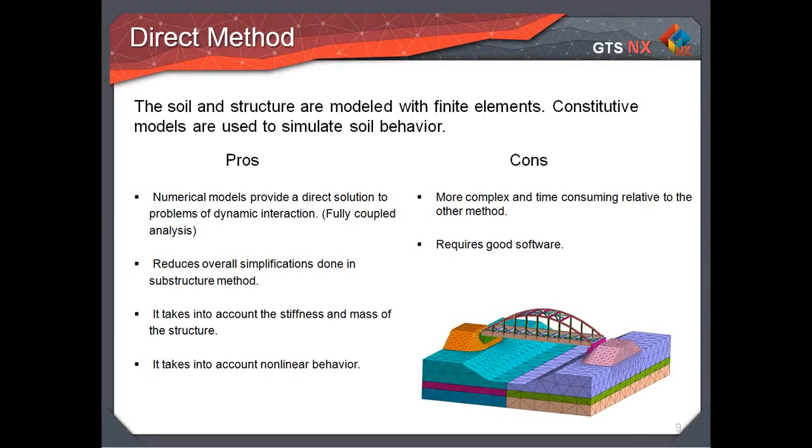There are some for rocks, like the generalized Hoek-Brown, but then there are some for clay, like the soft soil creep or Cam-Clay constitutive models. So there's a whole theory behind all these different behaviors that you can model or capture for a 3D element using these constitutive models, and Midas GTS NX has a long list of these.